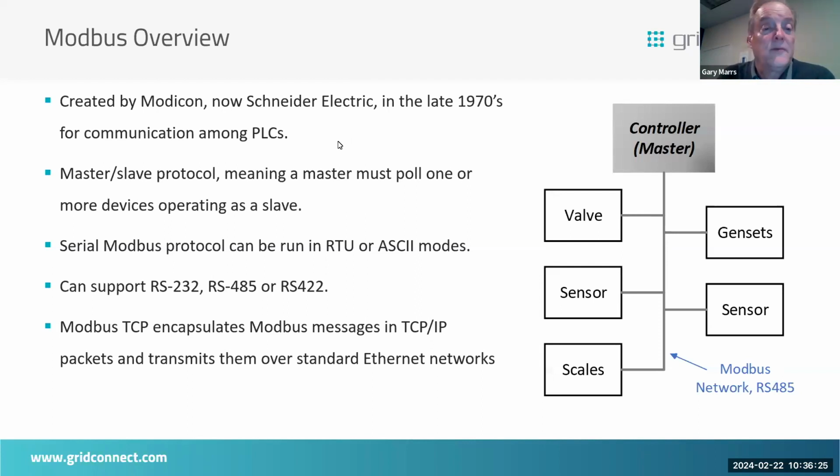It's a simple protocol. It's master-slave. And I guess one thing I want to say is this is an older protocol, so some of the terminology is a bit older. When we refer to master-slave, we're only talking specifically about Modbus. On the serial side, just the way serial data operates, you can only have one device initiating communication, and the other devices have to respond to the initial request. So it does kind of fit the application, but it's older terminology. So it's a master-slave protocol.